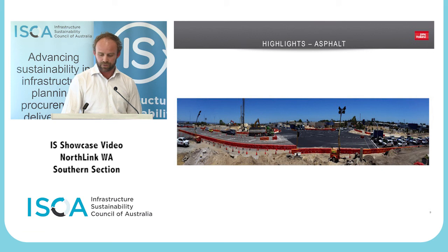The other thing with asphalt is that up until very recently, Main Roads didn't permit the recycled content of the asphalt to be more than 10%. So you weren't allowed to incorporate more than 10% of an old road into a new road. We've been discussing with them how we can improve on that. And that has come about through discussion with Main Roads, our supplier Boral, and ourselves.